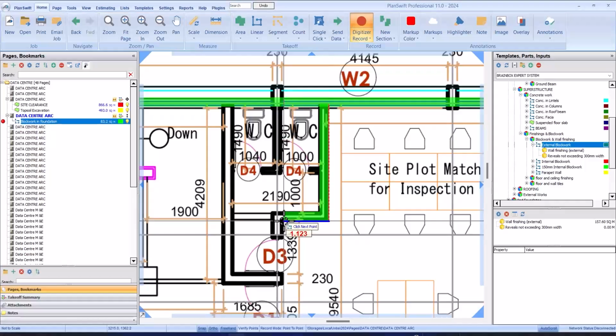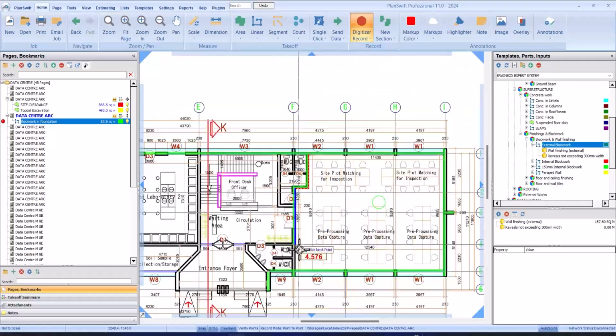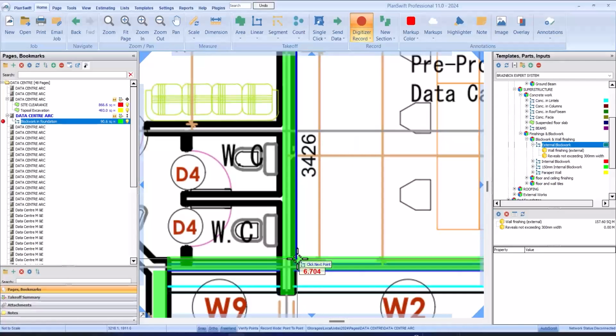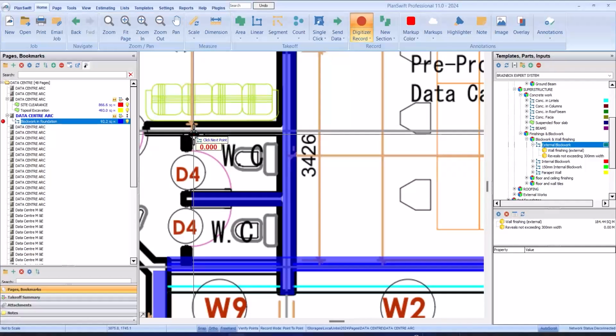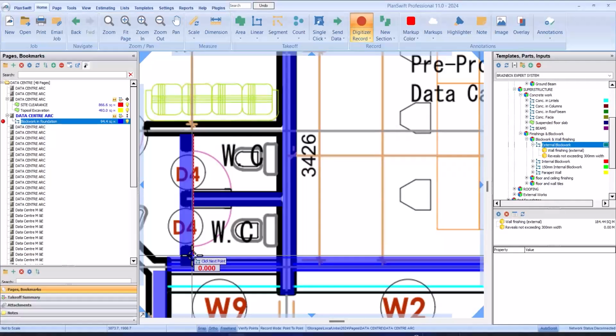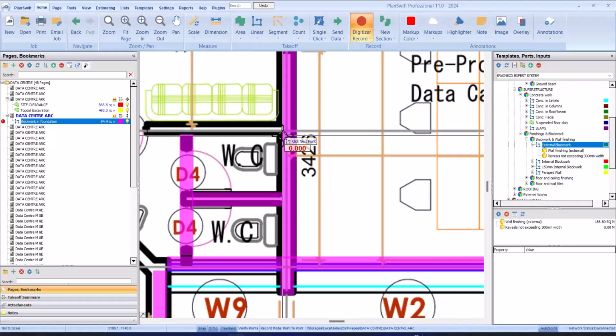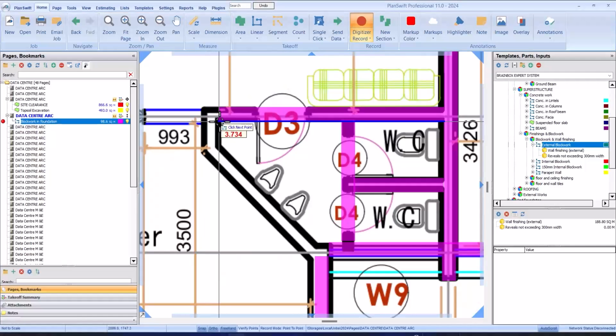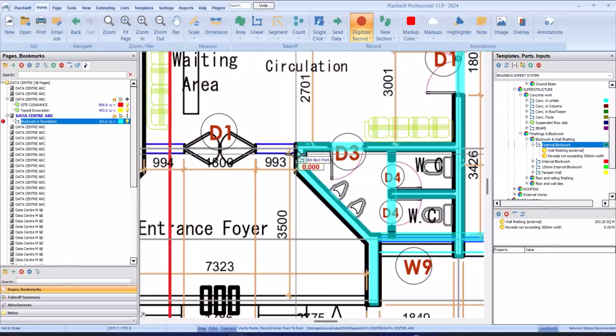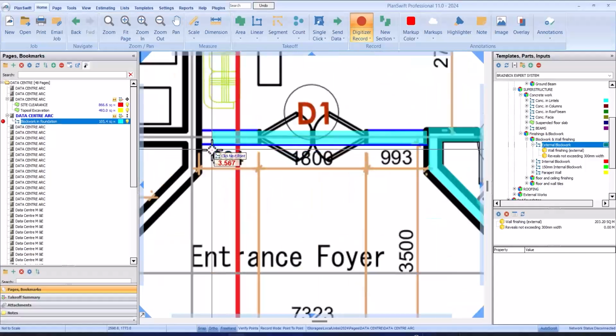And see, this is 150 mm block in the foundation. We're going to use 230. Then in the ground floor, we use 150. So all blockwork in foundation are 230. So we're not going to specify anything. We'll take it as a whole.